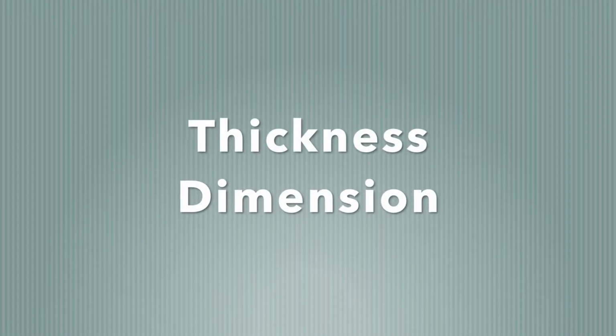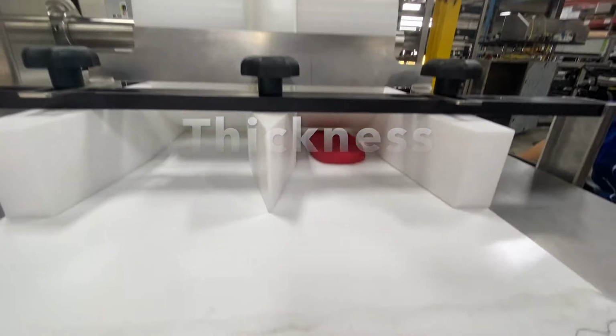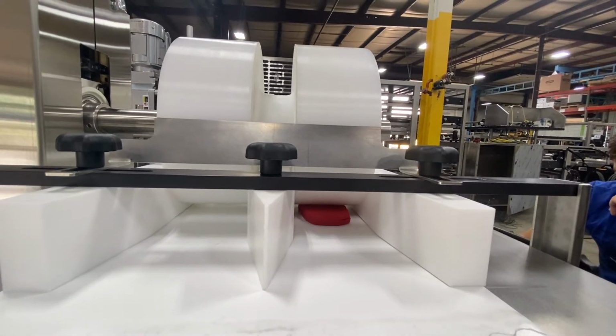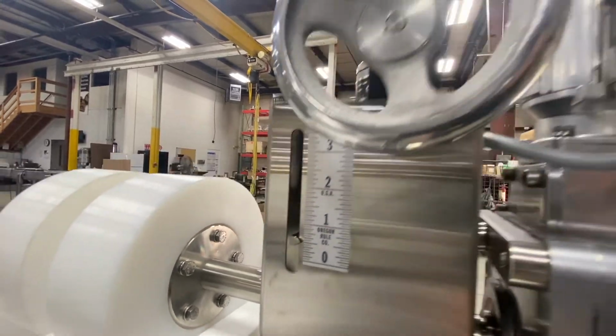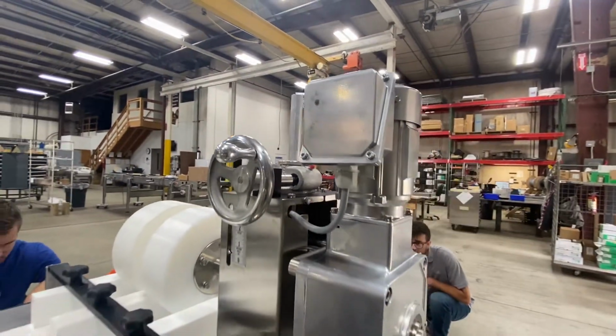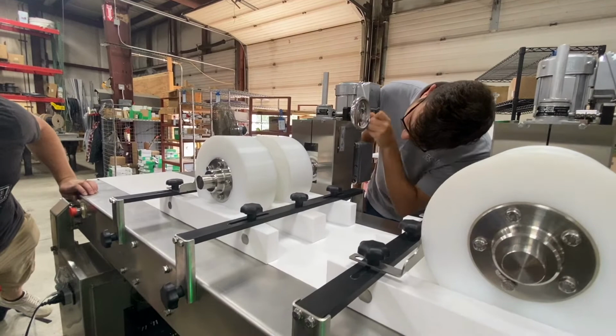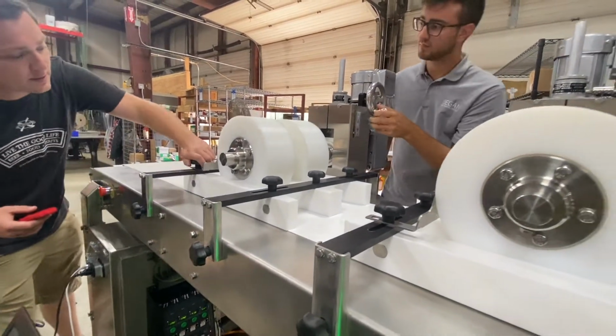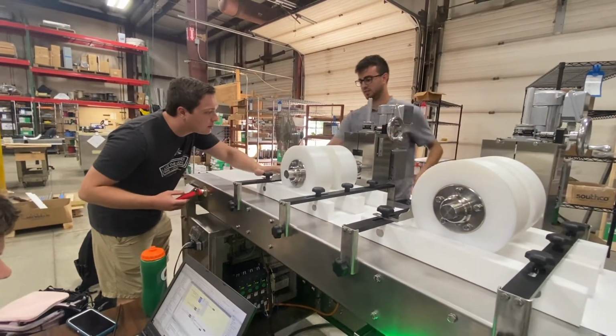The thickness or the height of the bar is dictated by the height of the pressing rolls above the deck. The operator can use these hand cranks to lift up and down the pressing rolls to a desired thickness. There are 2 pressing rolls. The first one acts as an initializer of the product thickness, while the second acts as a finalizer.